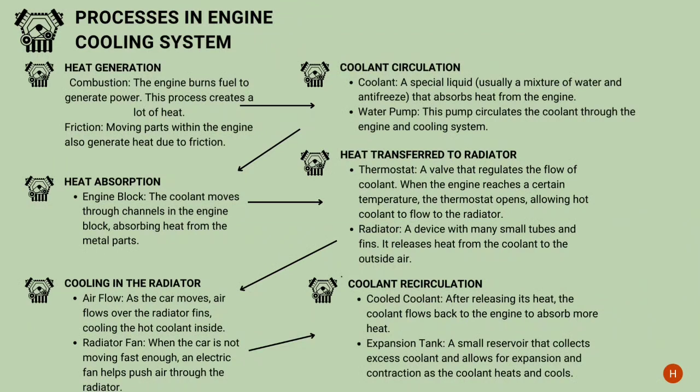The third one is heat absorption from the engine block. The coolant moves through channels in the engine block, absorbing heat from the metal parts. And the fourth one is heat transferred to the radiator. It consists of the thermostat and radiator, where the thermostat is activated when the engine exceeds a certain temperature, and the radiator is the medium to release the heat from the coolant to the outside air.